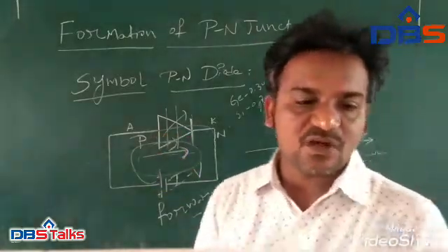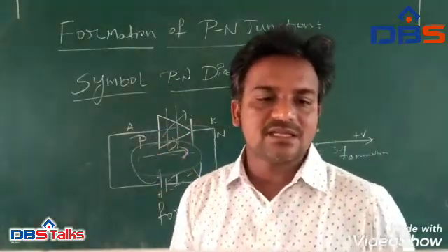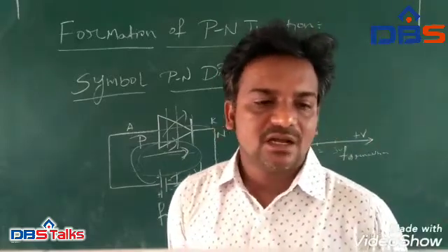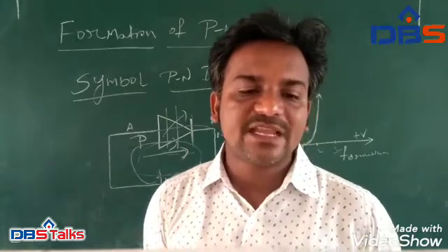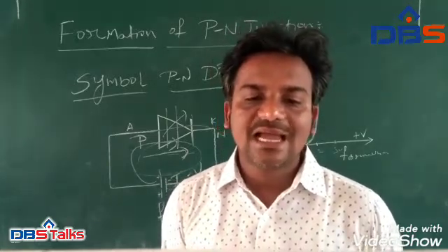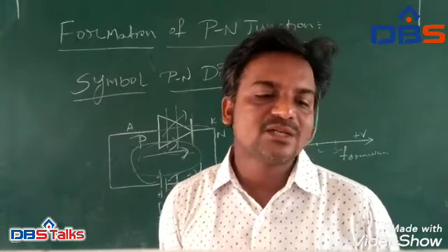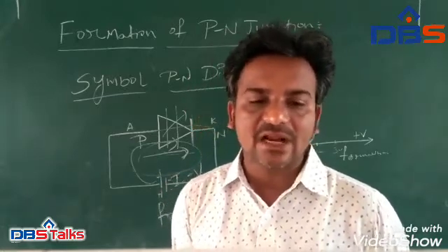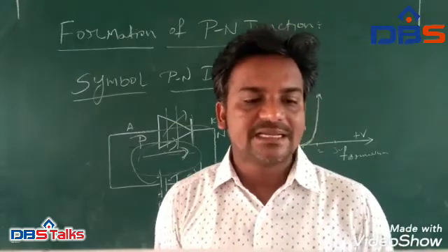That is the operation of forward bias. When a voltage is applied between two ends of the PN junction diode, it can supply free electrons and holes with the extra energy they require to cross the junction, as the width of the depletion layer around the PN junction is decreasing.